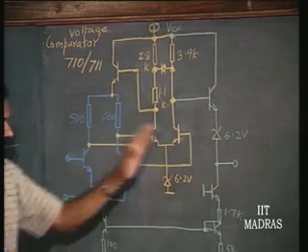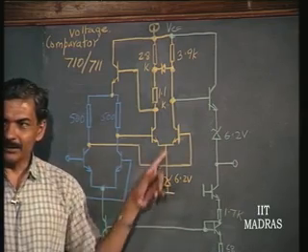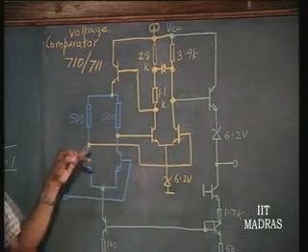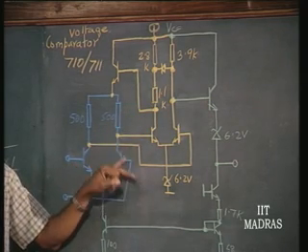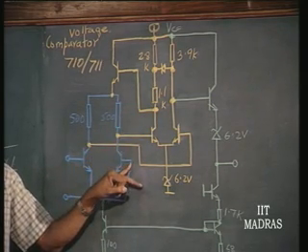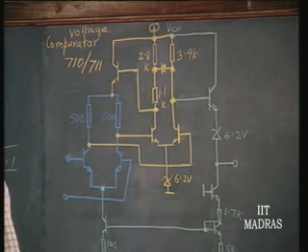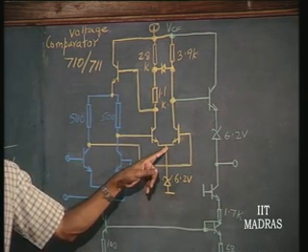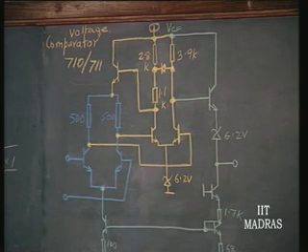So, the next stage, even though it is drawn like, okay, there is no current source here, this is voltage source, level shifter, right. The collector potential here has to be higher than that here, right. The collector potential here has to be higher than that of the base. So, level shifting voltage of 6.2 volts Zener is used, okay. But for AC purposes this is ground,